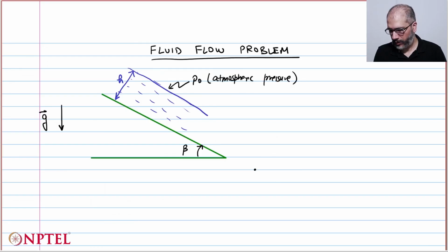So we'll say that this direction along the slope is the coordinate small x2. And remember, we always work in spatial coordinates when working with fluids, because it's always the current configuration that's of interest, not the reference configuration. And then the coordinate which is normal to the surface will be called small x3. And with this, small x1 is the coordinate that's coming outside the plane of this sheet. So that will be called small x1. This dot with a circle means it's coming out of this plane.